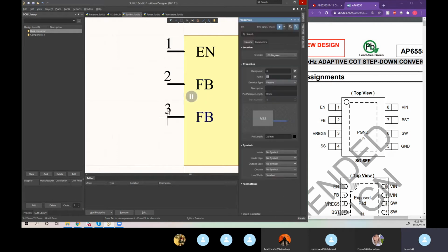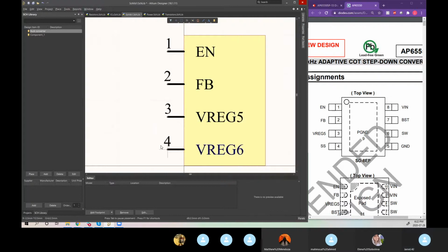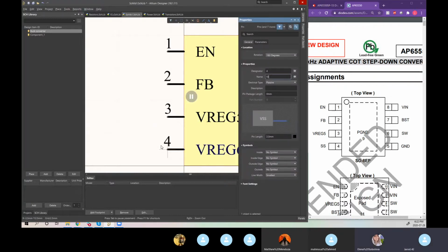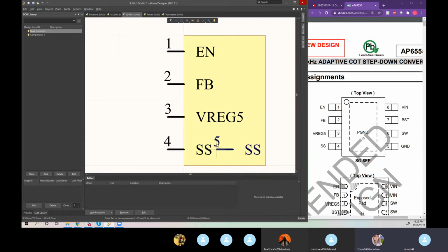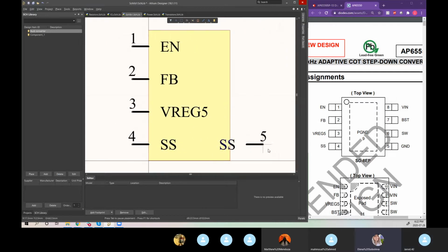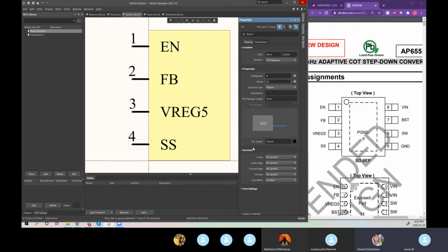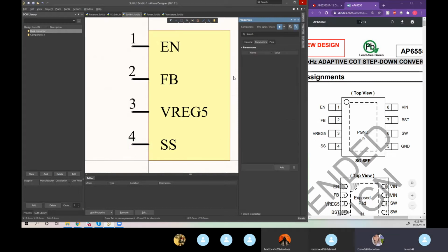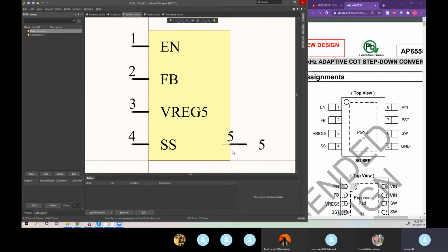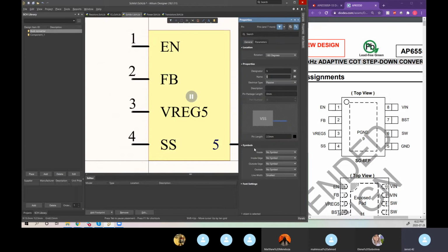Any questions as I just start filling this in? So whenever we make a new component, we need to start with pin number 1? Yes, you always want to start there. Also, you press spacebar to rotate it around. So if you're placing on this side and then you jump to the other, double space, you're on the back.